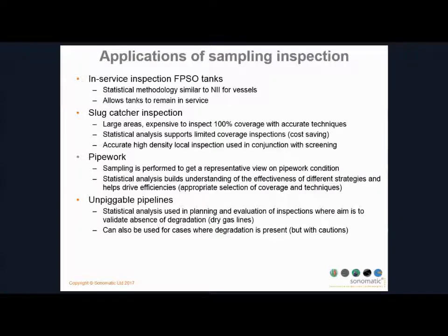So other applications are in-service inspection of FPSO tanks, the approach is similar to NII for vessels, and that allows you to carry out inspection with the tanks remaining in service. Slug catcher inspection, again, this is a case where there's a large area of interest, and 100% coverage with accurate inspection techniques wouldn't be economically feasible. So statistical methods based on sample inspection allow you to do a cost-effective approach.